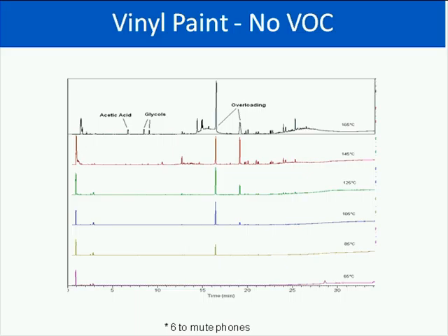You'll also notice at the higher temperatures we do see two humps, what we call highly unresolved multiple peaks, at around 14 to 17 minutes and 22 to 27 minutes. This could be a higher boiling point compound in the formulation, but we're not paint formulators, so we're not sure. If you wanted to analyze for it, you could probably do some different parameters to get those better resolved.